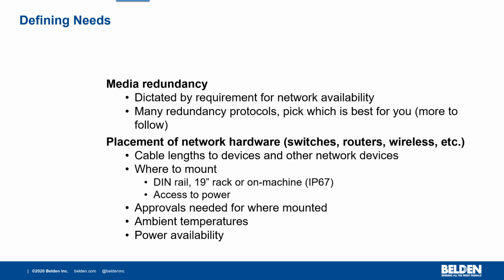And do keep in mind the availability and access to power, because this too is going to dictate whether you need a 24 volt DIN rail mount power supply or whether you can go directly into the switch with AC, which in a control panel is never a good practice, but nonetheless that availability is out there.